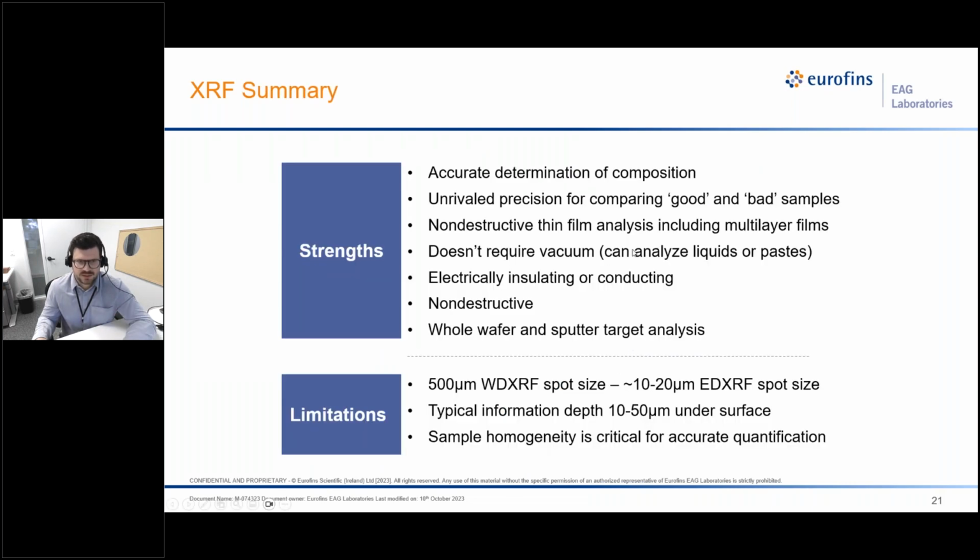All right, so in summary, as we discussed, some strengths of XRF are that it's a non-destructive technique, and it has the ability to measure solids, liquids, and powder samples. It's a great technique for measuring thin films, including whole wafer and sputter targets. On the other hand, some limitations may include the spot size needed for your type of sample, and the fact that sample homogeneity is critical for accurate quantification.